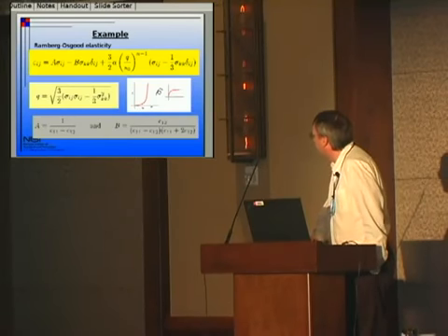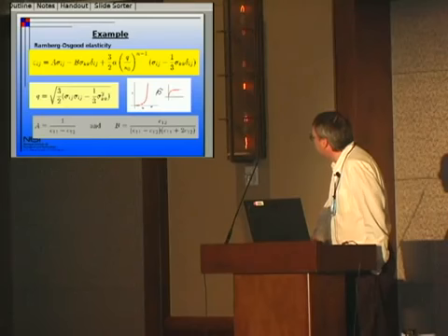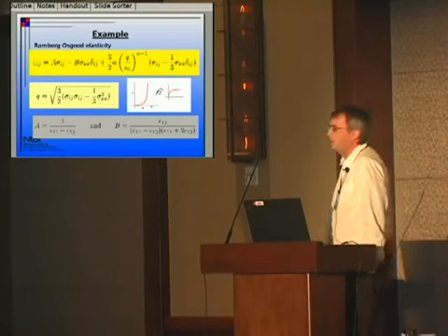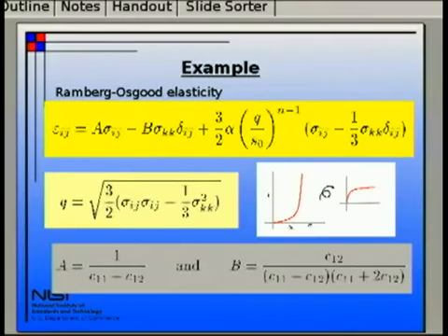The initial one here, look, I can point at this because this is all screwed up. So the first two terms in here are just ordinary linear elasticity, typical Hooke's law, and then there's this other term that says that the amount of strain that you have for a given amount of stress is this Q over some scale factor to some power, times a tensor that tells you how much of this is deviatoric.